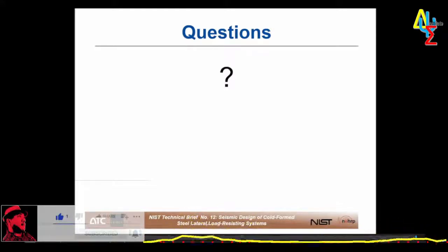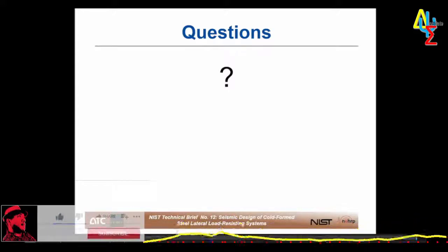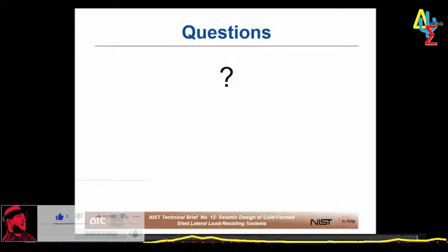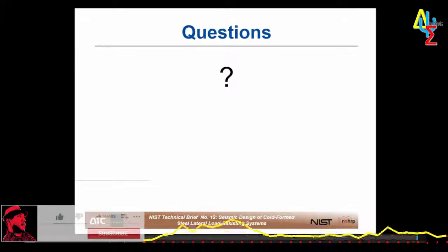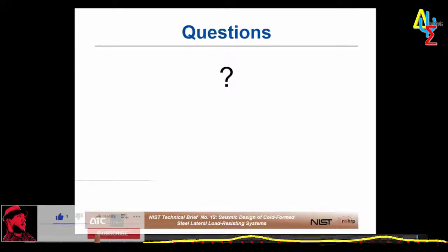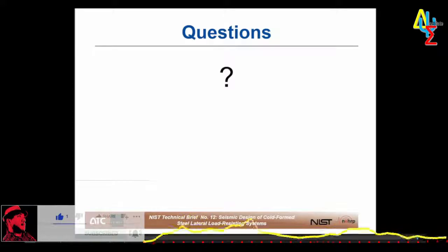If somebody asks, gee, is it possible to maybe develop or design a hold down that could dissipate energy? I'd say sure. Yeah, there's probably ways to do that, right? You could design some sort of a yielding mechanism in a hold down that could work. But you want to be super careful, right? Because you absolutely positively do not want that hold down to disengage, right? I mean, that is a critical part that's resisting overturning forces. So you'd want to tread very cautiously on any path that led you towards using that to dissipate energy.